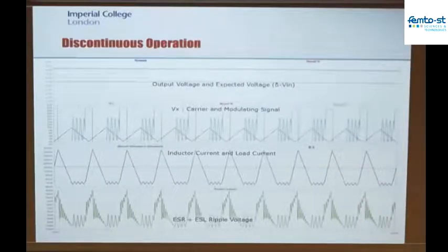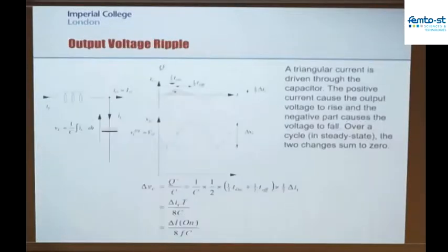So a circuit here, this is just an example of how when you build a piece of power electronics, if you look at how the circuit should work and you look at how the circuit ends up working, there are often these additional bits of stuff that you might not be expecting to play a role that end up playing a role. So we've unintentionally excited a resonance here between the diode junction capacitance and the main inductor in the circuit. At first glance, you probably wouldn't see that as an operating mode. But it's something that you should try and avoid if you can, this oscillation, because ultimately that's very high frequency and it's potentially going to cause problems with EMI.